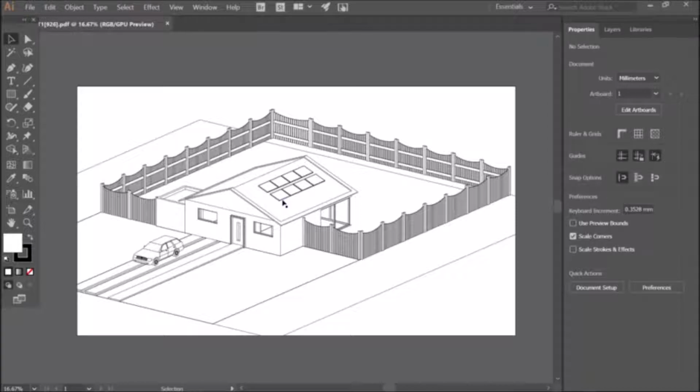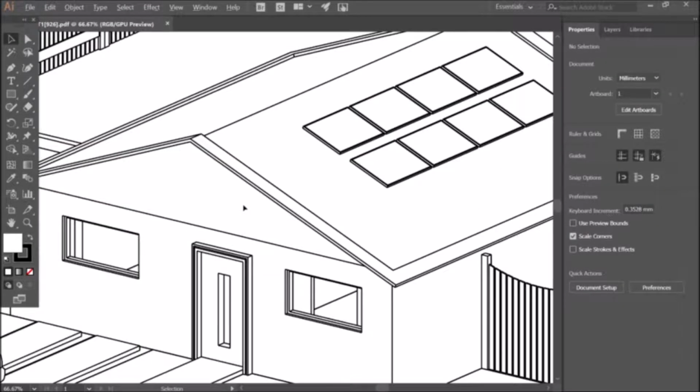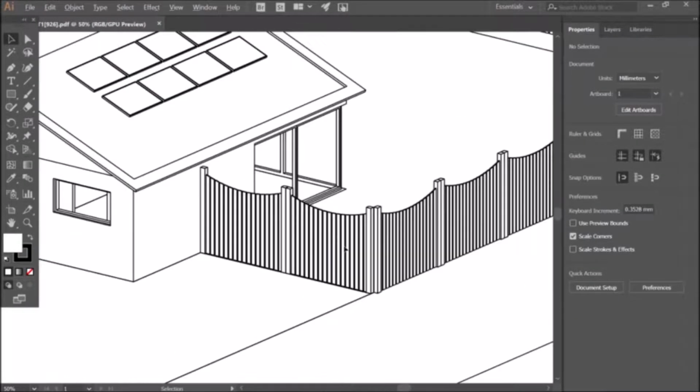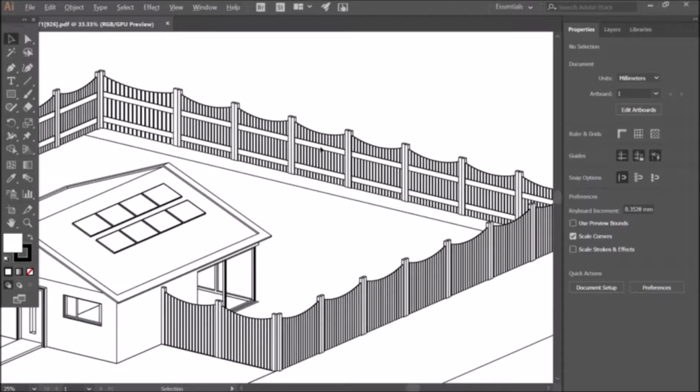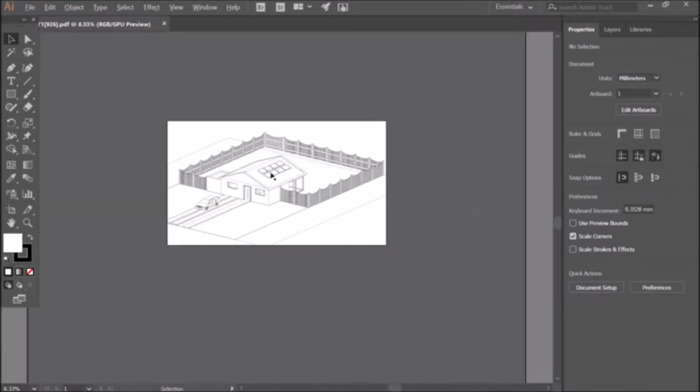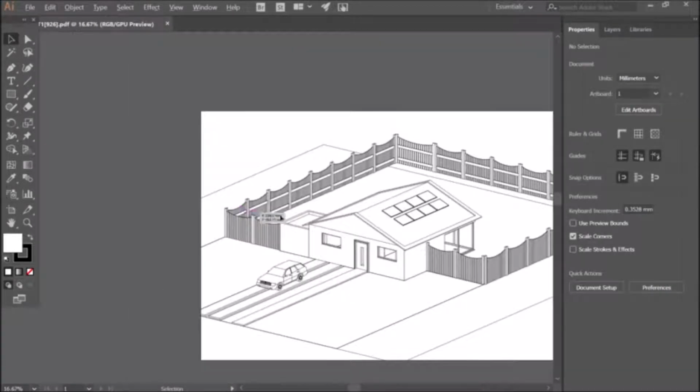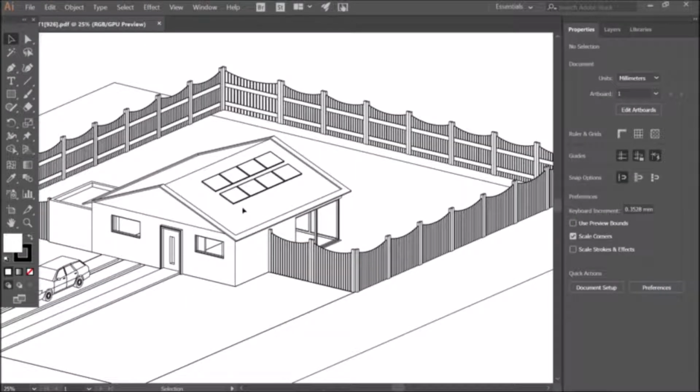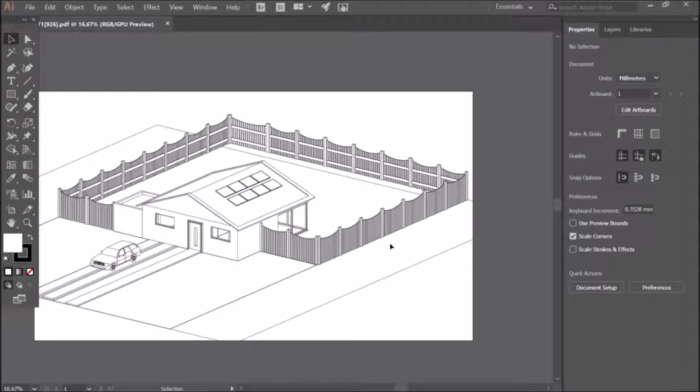So yeah, let's do the basic navigation of the software. All we're really going to use is the zoom and slide navigation. That's all you're going to need for this series. To zoom, we hold down the Alt key and use the mouse wheel, scrolling in and out. Wherever your cursor is on the screen, you zoom to that point on the drawing. It's very simple, a little bit different compared to some other software, but you will pick it up fairly quickly.